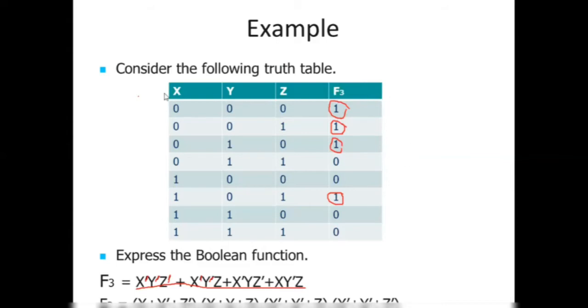Again, listen. What you are asked here is, using the truth table, write the Boolean function represented by this truth table. To answer that question, there are two main procedures you can follow. Either you can write the answer with min terms, or you can write the answer with max terms. So what's a min term?